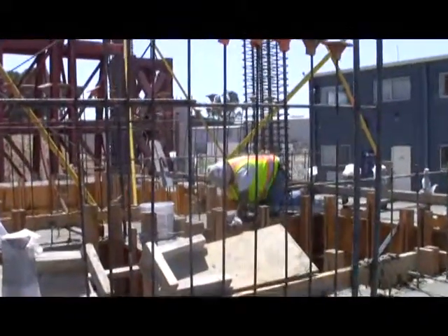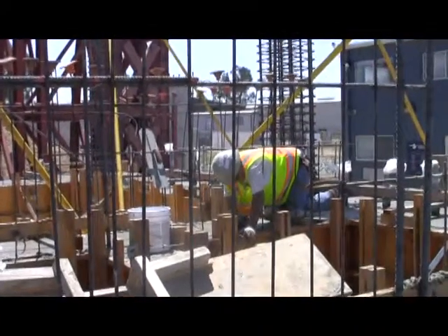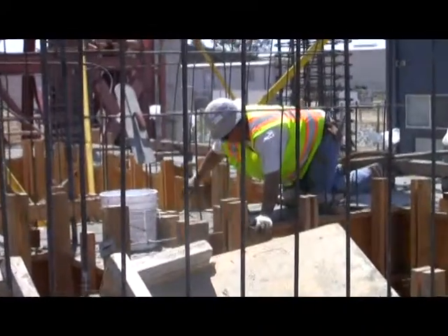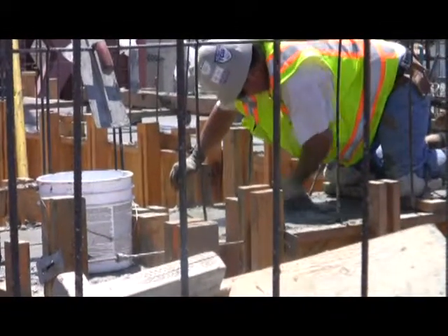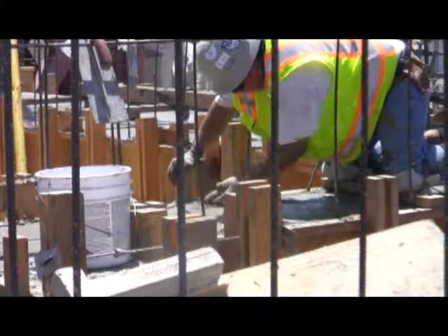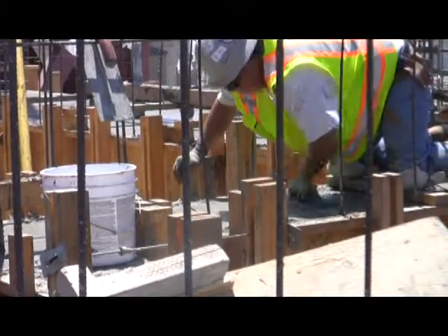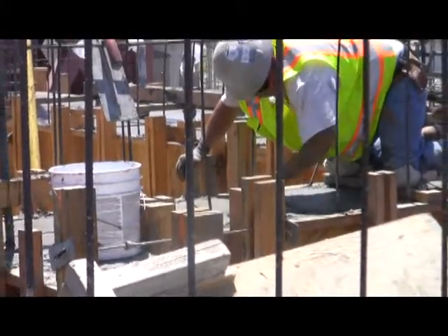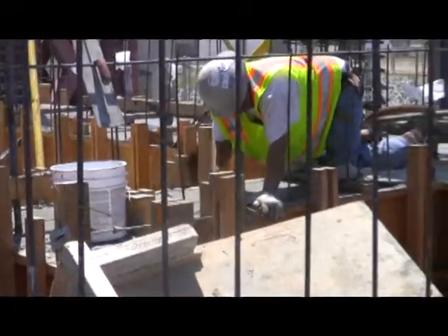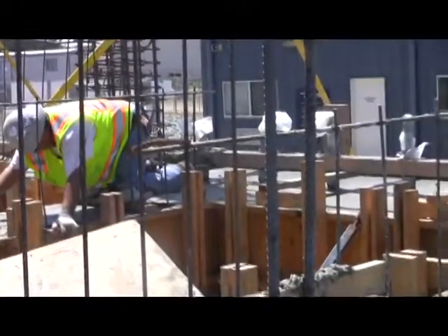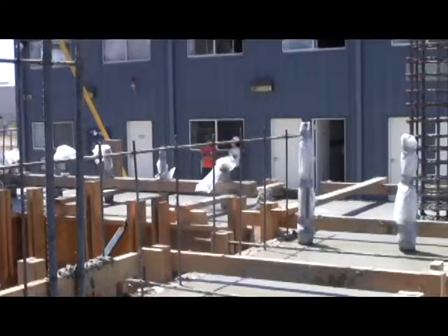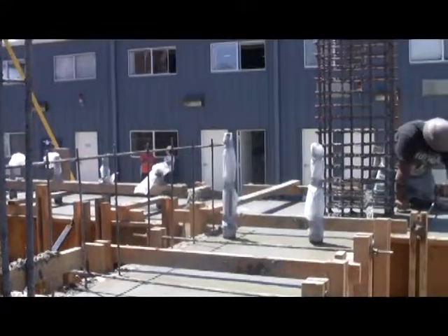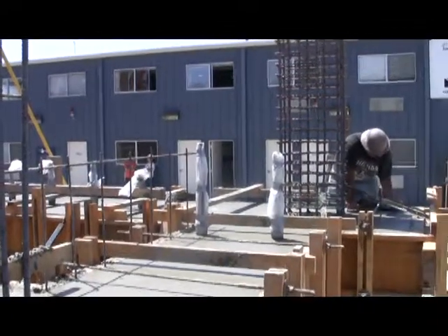The top surface of the concrete was then screeded to assure it was level and smooth, as well as bring near-surface water to the top of the concrete. A screed is a flat board, often made out of wood or metal, used to smooth the concrete after it has been poured. This process is done to extract the excess wet concrete and ensure that the top surface is smooth. After pouring and finishing, the concrete was left to cure for a few days until it was fully hardened and the formwork was removed.